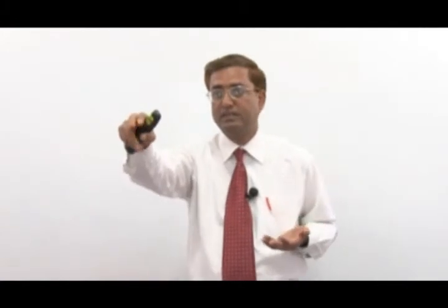The contact between the flash and die face is limited to an area which is known as a land. You can see here, initially the forging energy, then the filled one, and then the flash. When the flash is formed, it requires further heavy load, and then only the die will close. So that's how it shows.